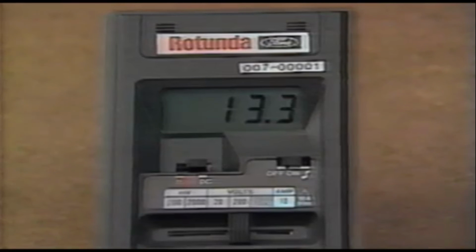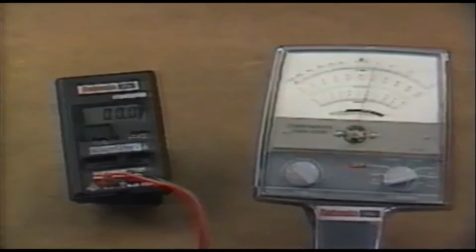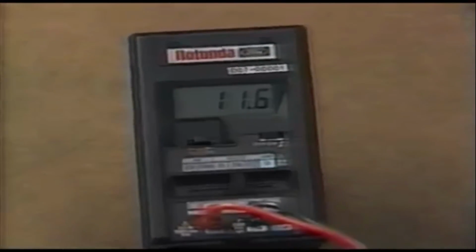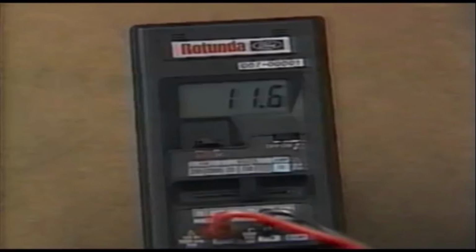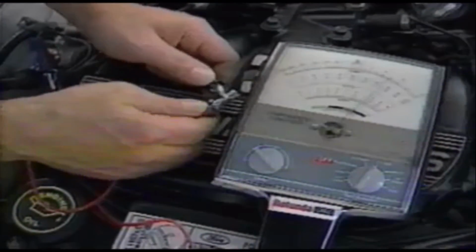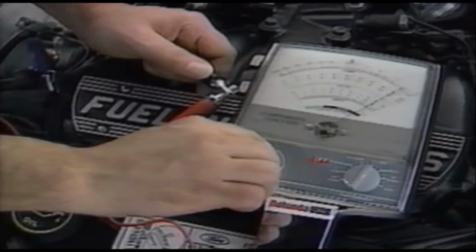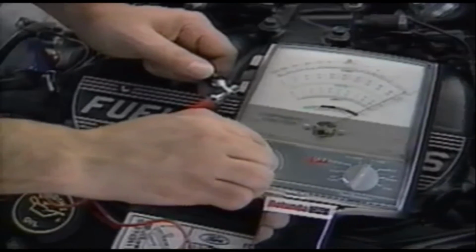Most of the electronic testing you will be doing requires the use of a digital multimeter for better accuracy. But more importantly, digital multimeters won't draw or deliver excessive current that will damage sensitive components. All your electronic testing should be done using a digital multimeter. And whenever you use either type of ohm meter, you must always zero the meter by connecting the test leads together and setting the scale to 0.